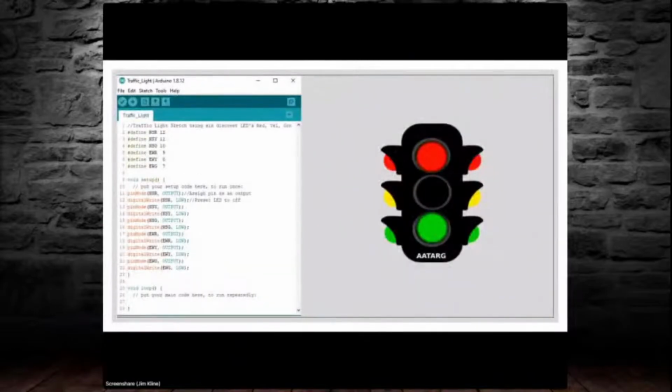When the Arduino first powers up, there is a remote possibility that the status of the output pins may be unknown. So prior to running the main code, a preset instruction is performed in the setup area so that we preset the exact state of each pin at startup.